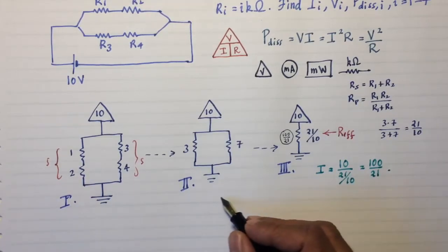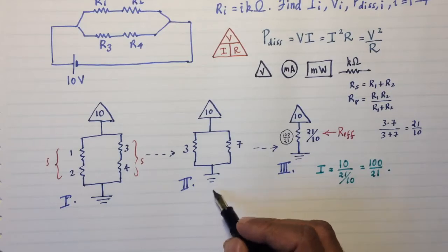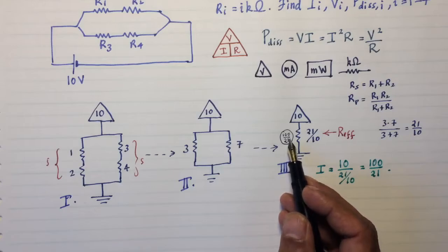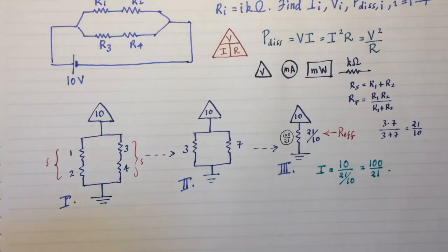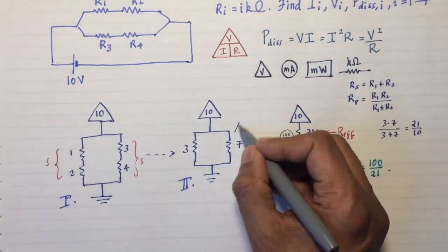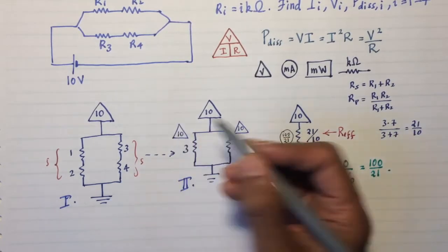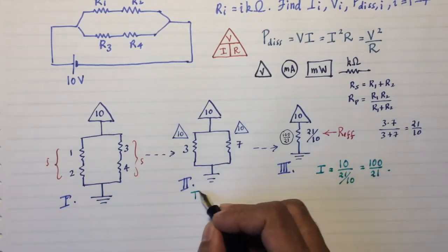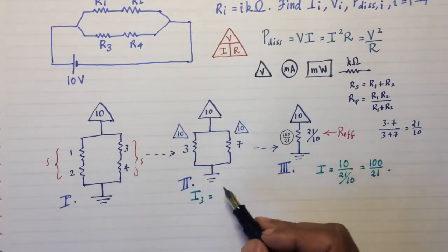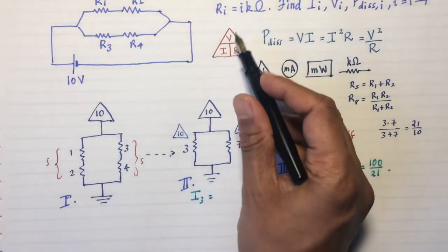So let's go to the second tree and see what we can get from that. The total current cannot be just written like that. You have to split it properly. However, I can write the total voltage immediately. Voltages across parallel elements are always the same. So I can write the total voltages immediately. For the current, here's what I do. I try to find the current through I3 and see what I get. By Ohm's law, that's V over R.